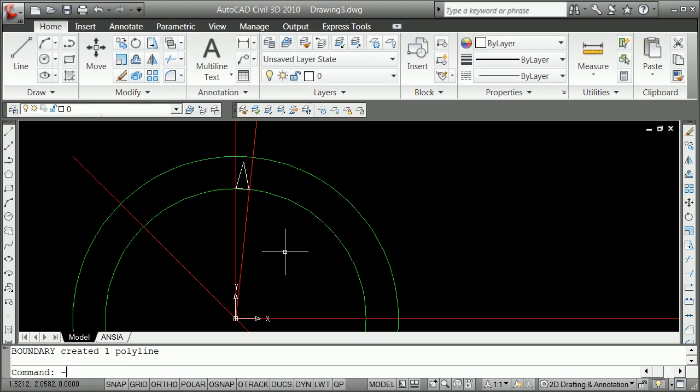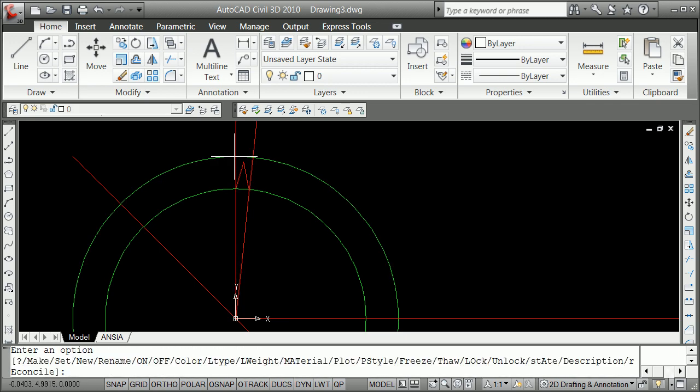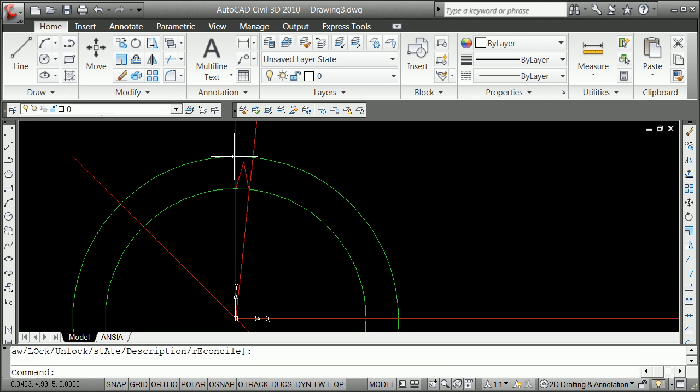I can now say -B, block name tooth. Insertion point is the intersection here. Select my objects. There it goes. I can now go finally -layer, new tooth. And now I've got a new layer, -layer, color, tooth, blue. Showing you different things as I try to get through here. I'm going to erase out those special lines I did.